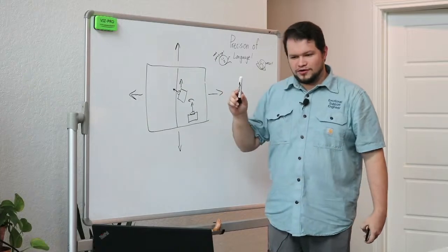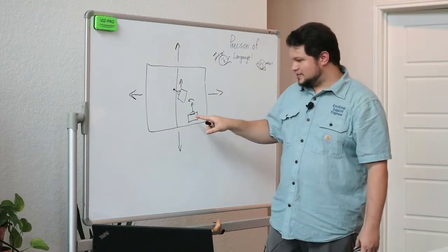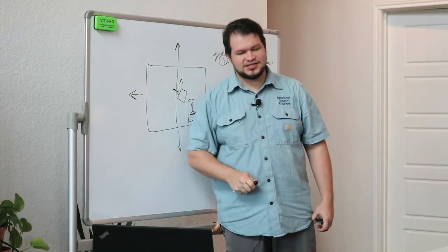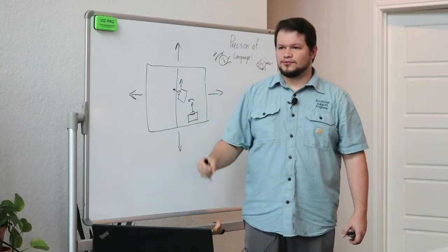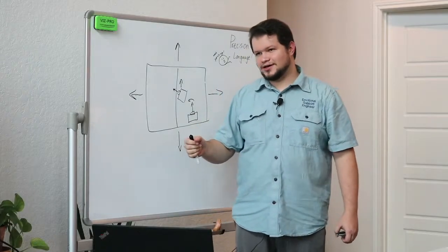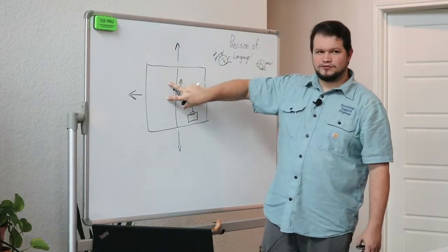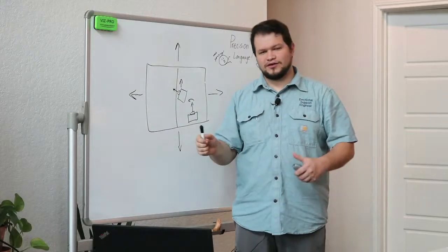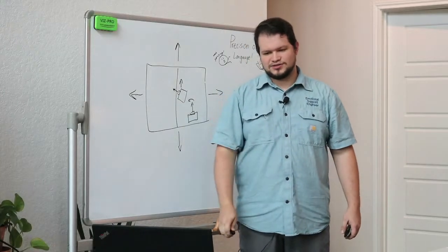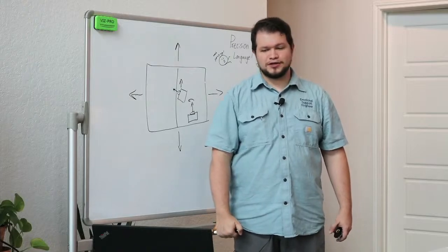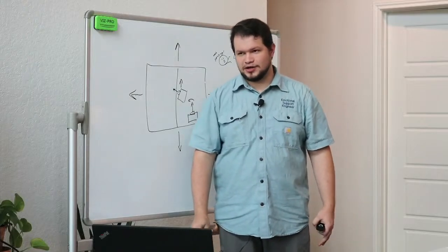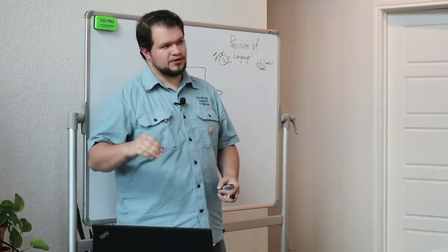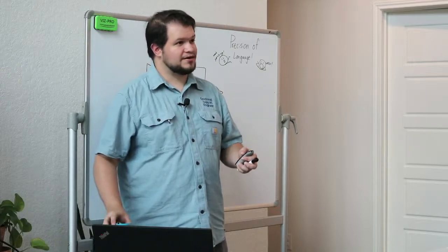The default for the Rev Control Hub is robot-centric, and we have had problems where, when you have interrupted power for whatever reason, even if it's not a complete shutdown, it will reset the IMU on our control hub, and it will switch us from field-centric, which makes strafing and driving kind of easy, to robot-centric. If you're not used to driving one way versus the other, it can really throw you off. So some people have resolved that by using an external IMU that does not drop your position when you have drops in your amperage or static shock, for example.